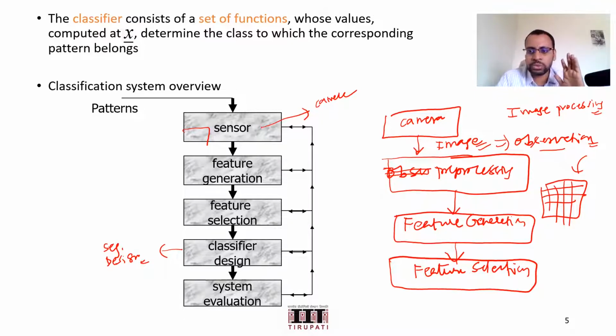So I want you to now perform an enhancement of the speech signal. How do you do that? It's a 1D signal. How do you do that? Sir, noise removal, right, sir? Yeah. How do you do that? We pass it through a low pass filter, since we have an idea that such sound produces high frequency noise. Very good.